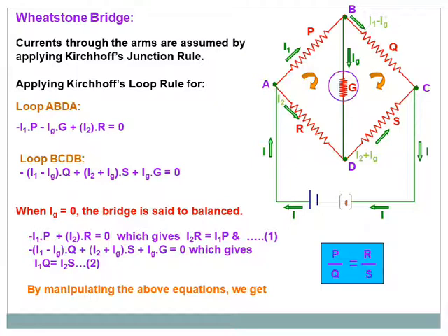And you can see another quantity, a galvanometer, connected between 2 points, B and D. So that works like a bridge between A and C. You can see from A to C 2 resistances in the upper part of the loop, and below there are 2 resistances. So there are 2 paths from A to C. A, B, C is one path, A, D, C is another path. Between both paths, there is a bridge. In the bridge, we have connected a galvanometer.